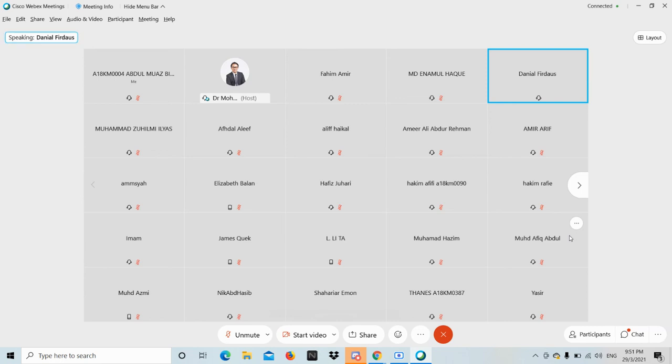Yeah. Yes, but let's talk about Honda. I don't like Honda, but I'm really fascinated with their technologies. What you say is true. They compensated for that because they have the VTEC technology, and they know that their VTEC system has a better advantage. They lose on certain parts by having a shorter stroke. That's the main purpose, they have a shorter stroke compared to other engines. If you're talking about the bore to stroke ratios, they have a much shorter stroke.